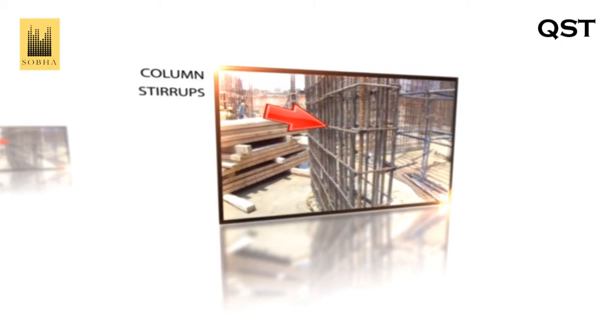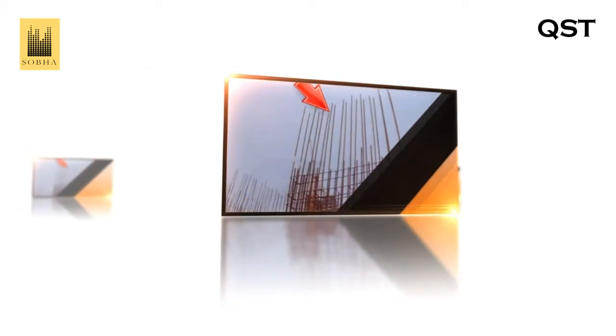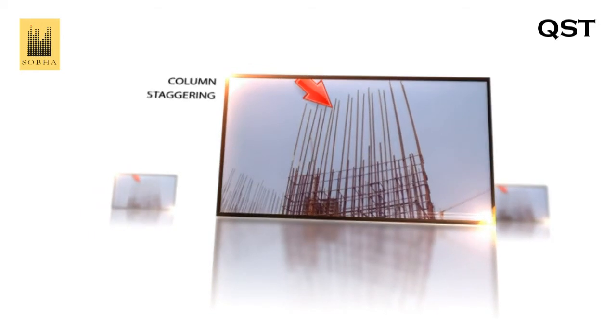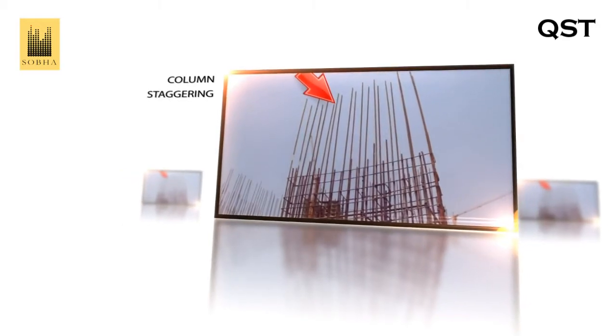Stirrups. The shear reinforcement for beams and columns are called stirrups. This image shows the stirrups in a column. Staggering. Staggering is very important in column reinforcement. Vertical bars of column shall be lapped in regular zone only, and it should be staggered, that is, not more than 50% of bars can be lapped at one section. In addition to that, minimum clear vertical distance between lapped bars shall be 0.25 times lap length.